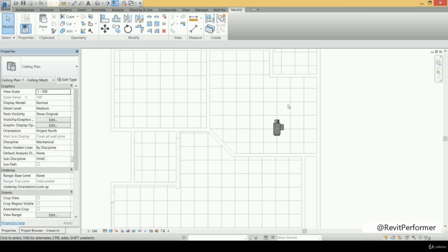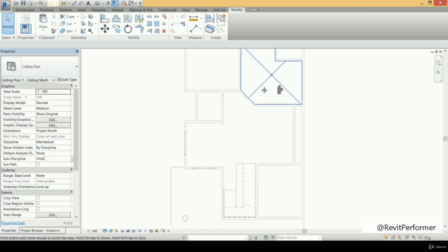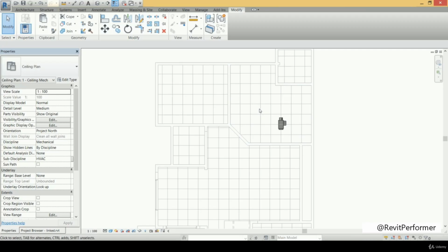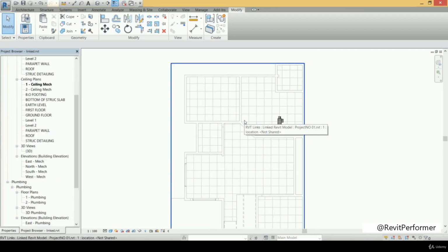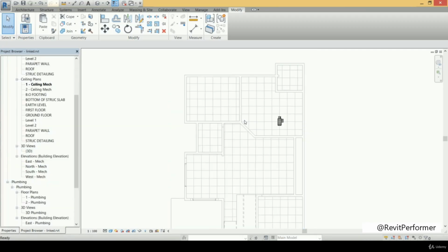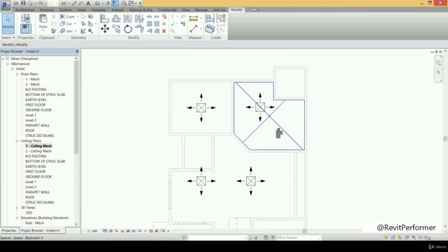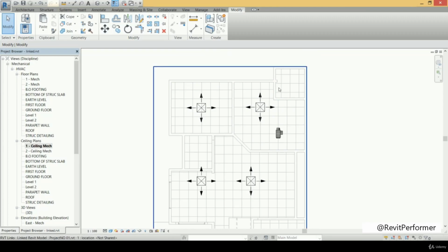So if you remember, we have made the air terminals design on the previous tutorial for that room and that one and that one and that one. So I can paste the air terminals again at that ceiling. I have copied them and I can paste them here. Those are the air terminals we have, and our target now is to make the variable air volume to feed those air terminals or to feed those zones.